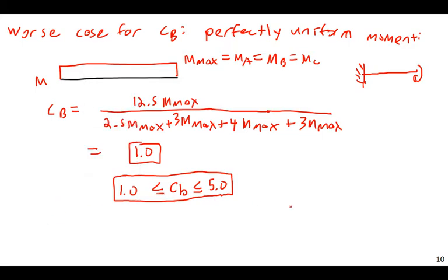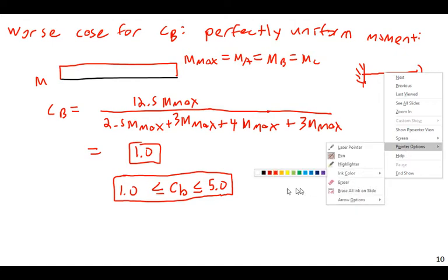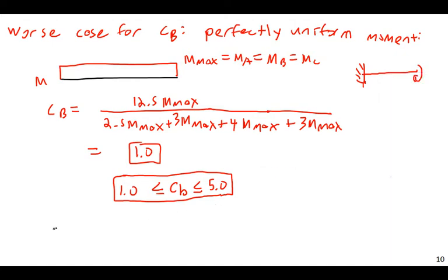However, this also tells us something that we can use, and this is very useful, especially for design. This does give us a value that we can assume. So CB, generally for lateral torsional buckling, if I want to remind you of equation F2-2, how is CB used? Using CB, if you remember, the equation for lateral torsional buckling, F2-2, uses the equation like this.